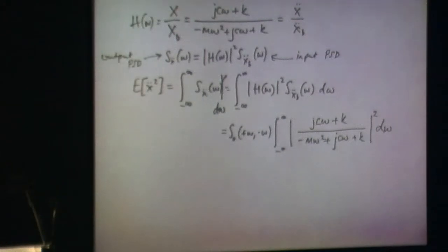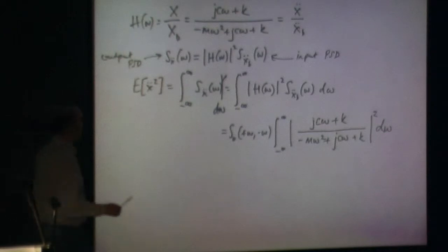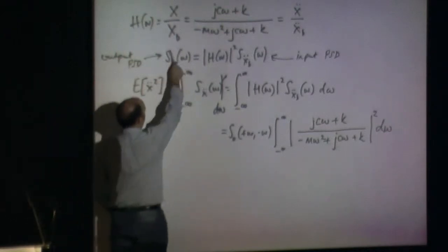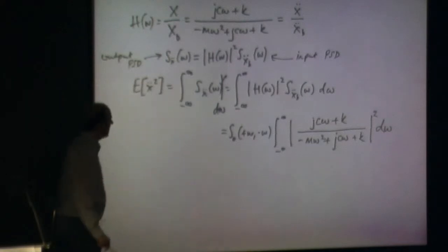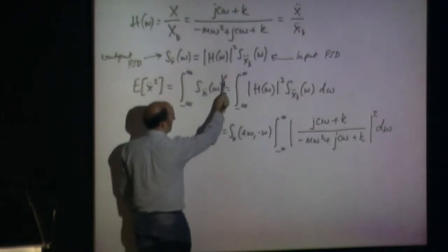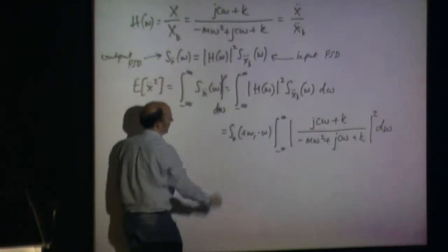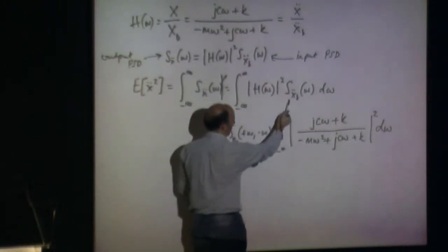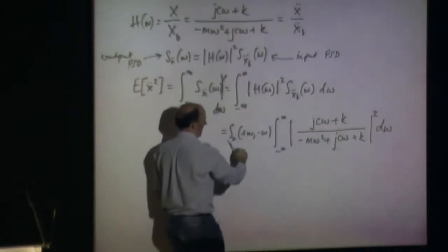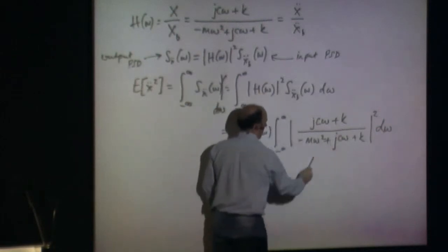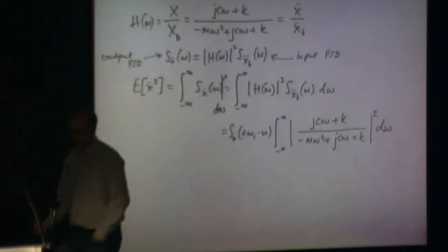So that line gives the relationship between the input power spectral density, which we've been given, and the output power spectral density, which is what we're looking for. The integral of this will give me my mean square value, okay? And so if I integrate that with respect to frequency, with the d omega in there, that equals the integral of this. This is a constant, we've been told, so that can come outside. And then obviously we integrate this here, and we use our integral identity for that.